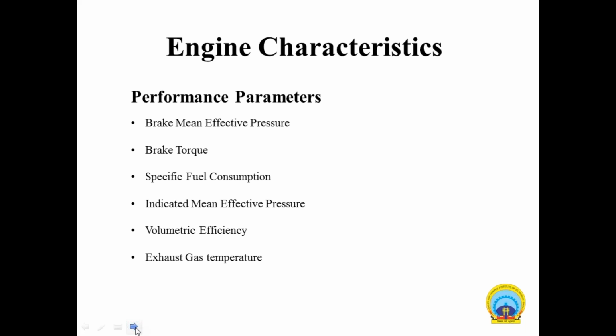Then your exhaust gas temperature. So exhaust gas temperature in diesel engine exhaust gases varies with speed and load. High loads and high speeds result in the highest temperatures. Generally, temperatures of 500 to 700 degrees are produced in the exhaust gases from the diesel cycle, and this is our 100% load. For no load, I think it is 200 to 300 degrees Celsius.